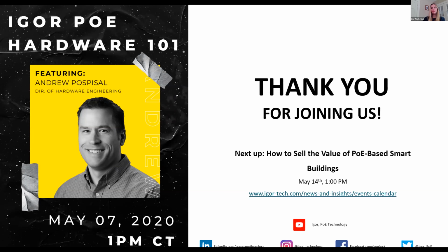Great. From Jose Maria: how do you protect the LED luminaires in the case of an overcurrent on a program failure? Is current control only via software? Typically the nodes will be programmed for a certain max current based upon the fixture they're connected to. Whether Igor, one of Igor's partners, or the fixture manufacturer does the programming, somebody will make sure that maximum milliamp level is set correctly, whether it's 700, 1,000, or 1,400 milliamps, so that the 100% dimming level corresponds to that milliamp level.